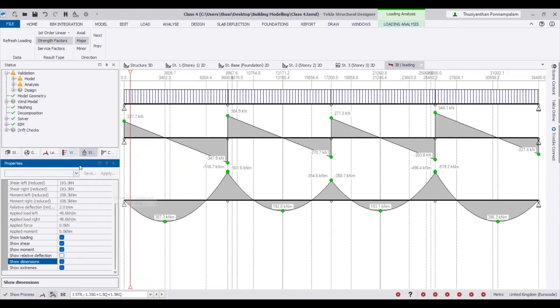Understand? Okay, now you see, this is my expected bending moment diagram, as I explained earlier. So we can create it. Some people don't want to make it pin here, so they can see some moment here, but it's my decision, so I make it pin. So at this joint, I don't transfer any moment.